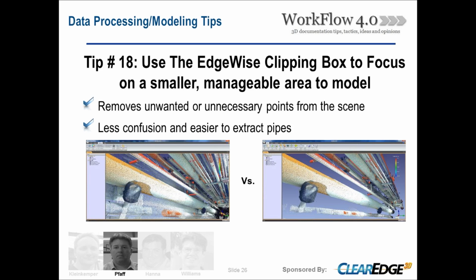If you utilize work sets in Revit, that allows you to take out and put back in or replace entire model sections without having to go through and pick individual items out for deletion. It gives you a lot more control and also allows you to unify your team as far as being able to have multiple work sets going as far as the MEP modeling goes.